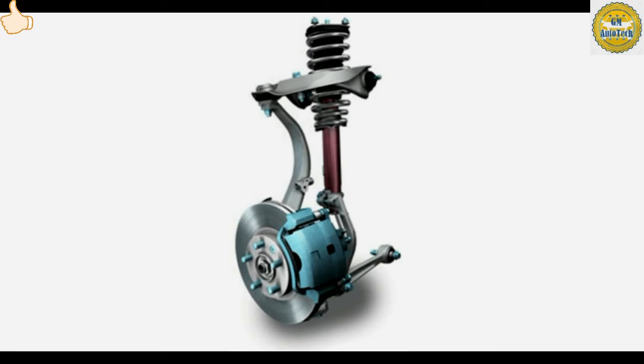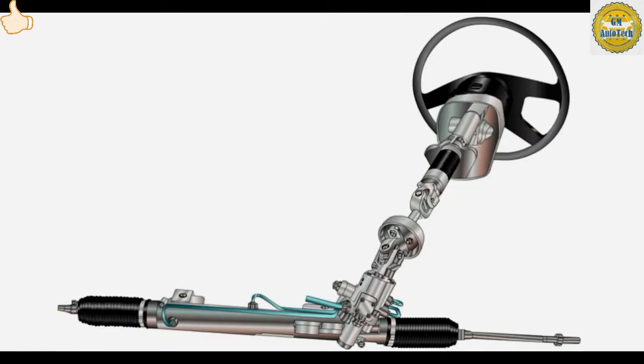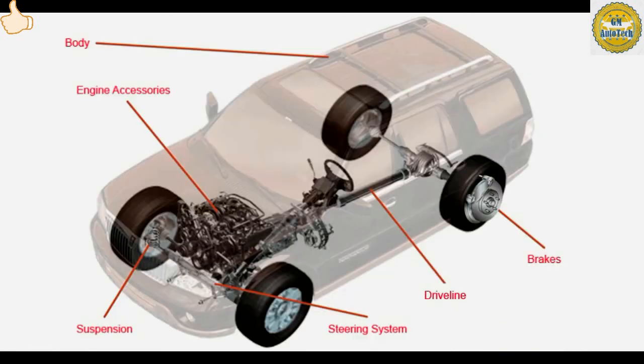Bushings can cause noise if they're worn, deteriorated, or contaminated. Noise can also be caused when an outer or inner bushing sleeve tears loose from the rubber and rotates. Steering gear, tie rod ends, and ball joints are mechanical components subject to a great deal of wear. The linkage components can cause noise if they are loose, binding, or seized. The steering gear could cause noise if the gears are worn or improperly lubricated.